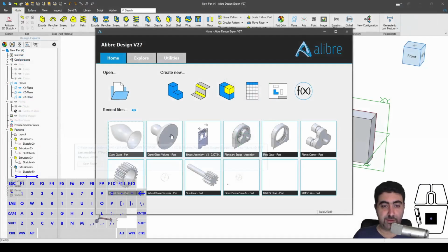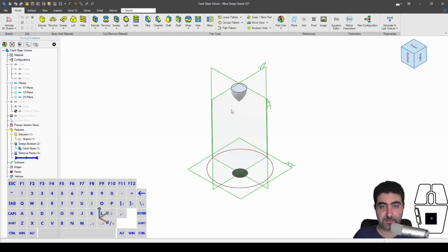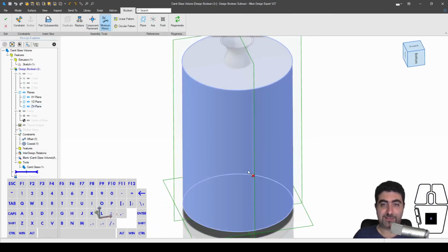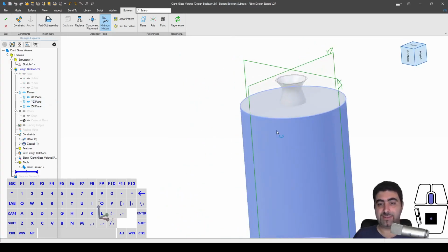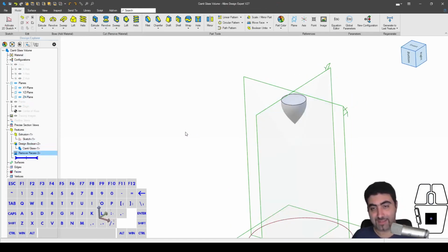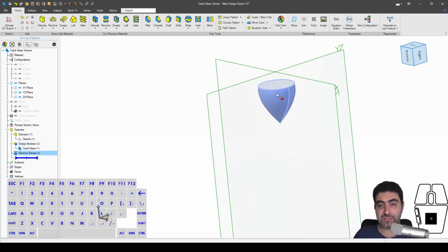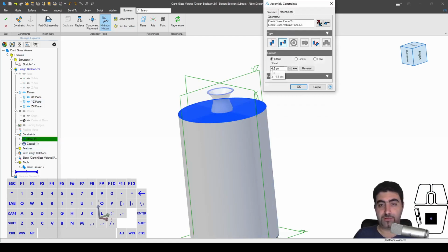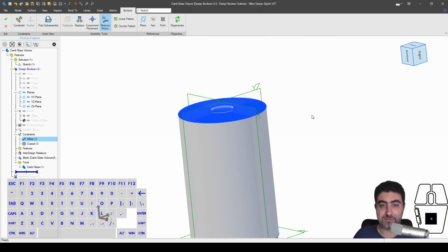And let me open the Chianti glass volume. Okay, I expected this. Right. It has updated correctly, right? You see what happened, guys? It's just that the offset that I had used in the Boolean now becomes non-practical, right? So let's make that 5 millimeters or half a centimeter.